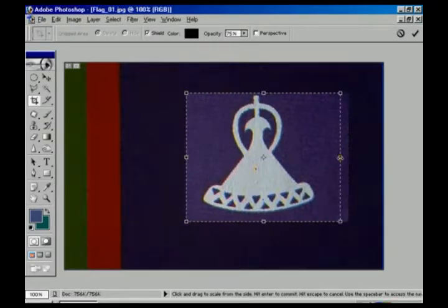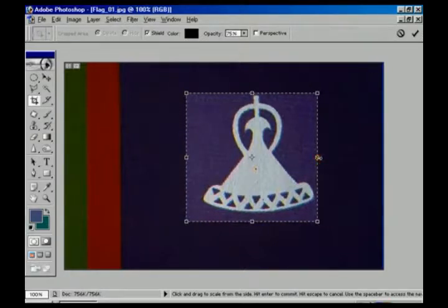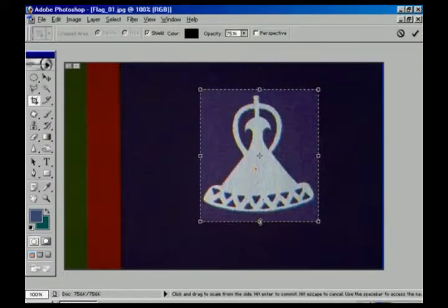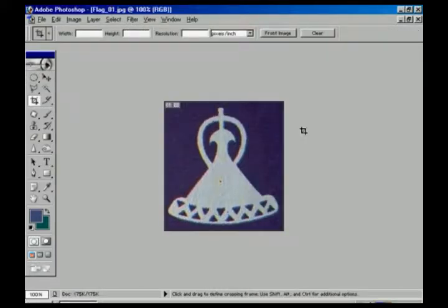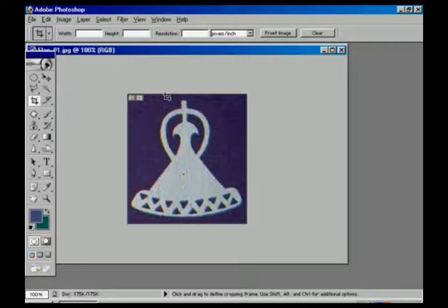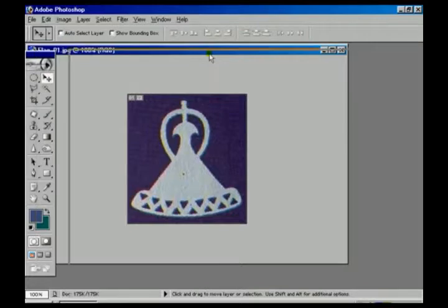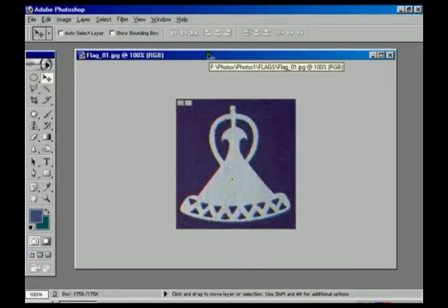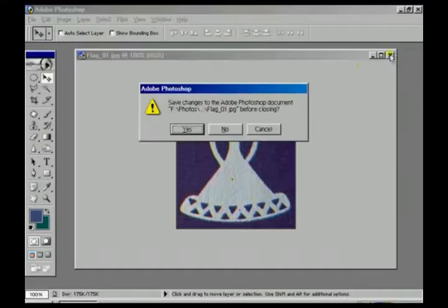The highlighted area is showing on the image, and we can adjust it. There are six vertex points. We can pull each of the vertex points to adjust it to the image and press enter. At that moment the image is totally selected and treated as a single image. Now minimize that one, select the move tool, and close the application.